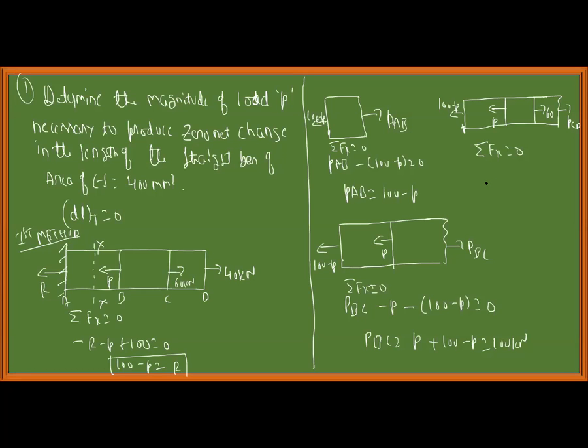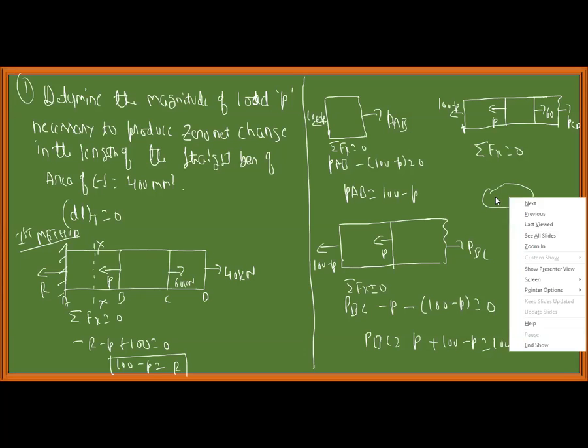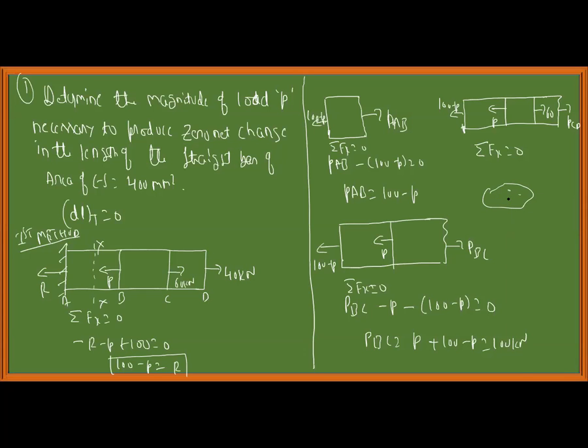Stress varies from point to point and plane to plane. If I take a body like this and consider a point, the stress at this point is different from the stress at that point. But I can also pass infinite number of planes at a point, and on each and every plane the stresses will differ. If we know the stresses on three mutually perpendicular planes, by using transformation we can find the stresses on any other plane.